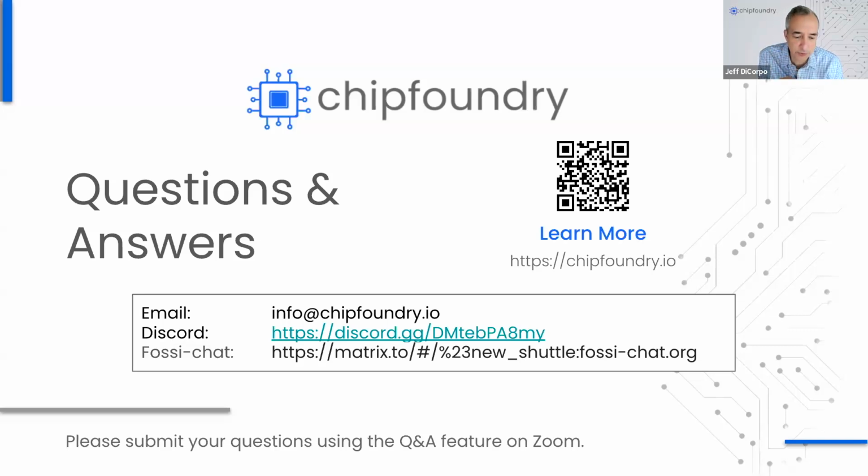For individual die, the solution allows you to submit a project die just like you do on an MPW, and run that at volume, starting anywhere around 10K up to 100K, and that would be the same project running at that volume. You can actually do multiple different dies to get different variants, but they would be separate projects and separate slots typically.